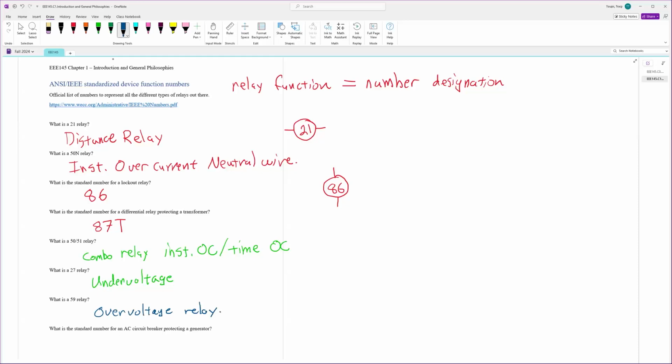Right. And just to give you an idea, we could set an equation, like an if statement, we could program: if X is greater than, I don't know, 12 kV, or let's say 15 kilovolts, 15 kV. Okay. If our read value is above 15 kV, then we'll trip the circuit breaker and we'll open the switch. Okay, so that's how an overvoltage relay will operate. And we could choose this 15 kV or another value. It could be 30, 80, 150 kV, whatever we want. But this is the logic the relay will look at for an overvoltage relay.